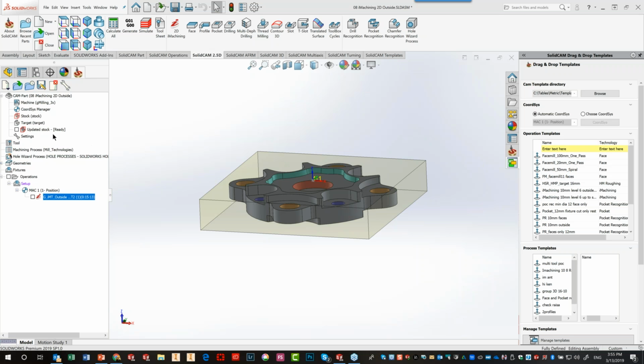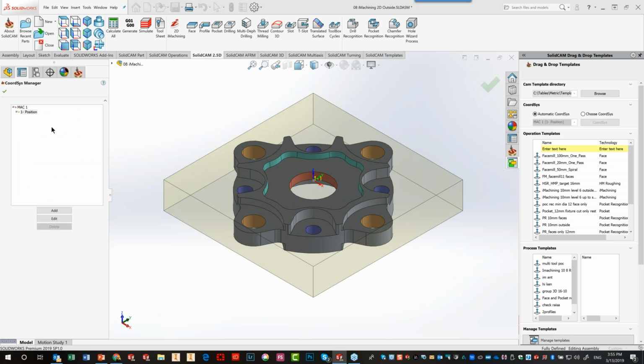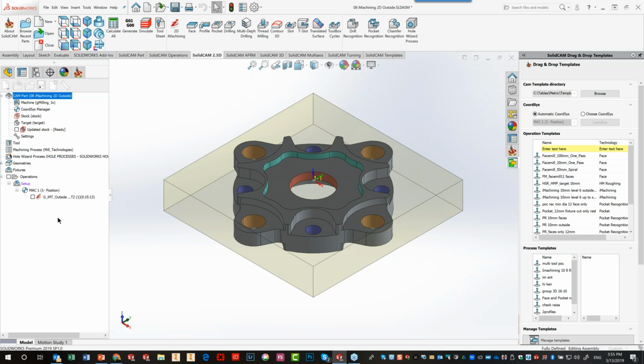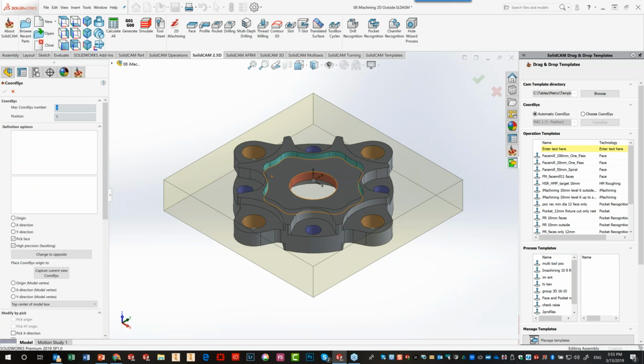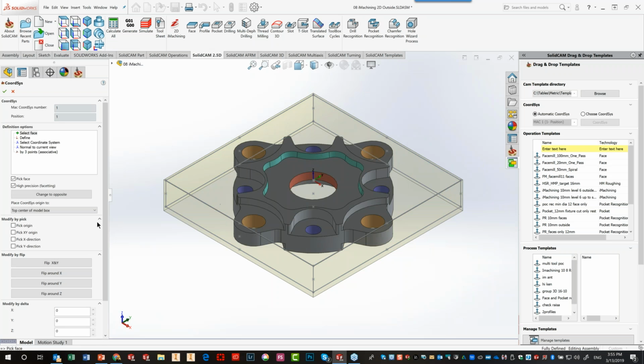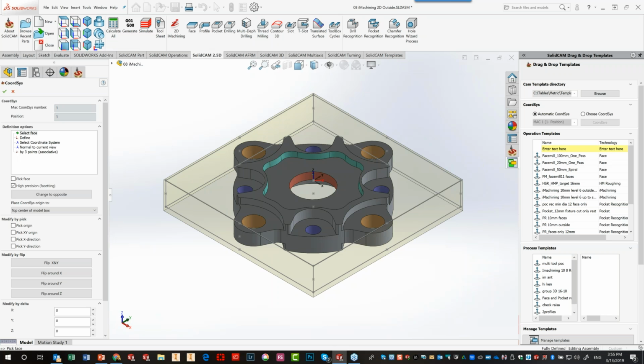Yeah, usually the box definition is based off, let's go over the system. Let's open up everything so I don't have to go back and forth. Okay, if I go into my coordinate system, and we'll do an edit over here. Edit coordinate system. Click over here. Go down to the bottom. And rotate around Z, say 45 degrees, something like that. And accept that.